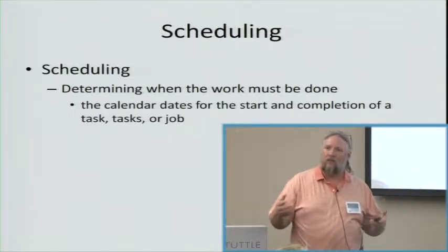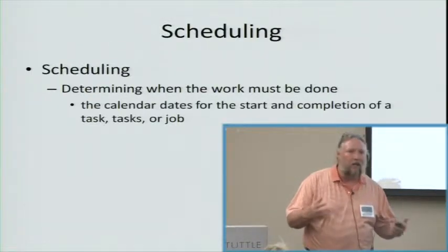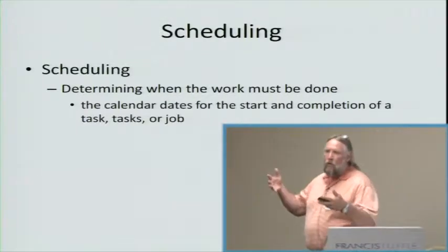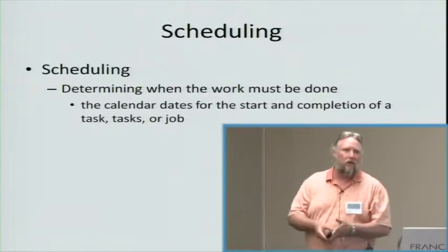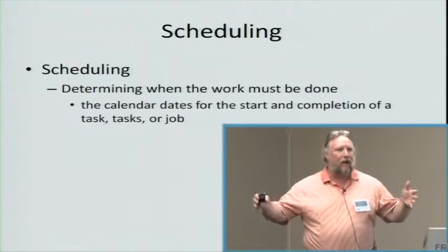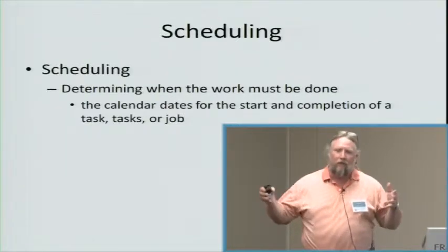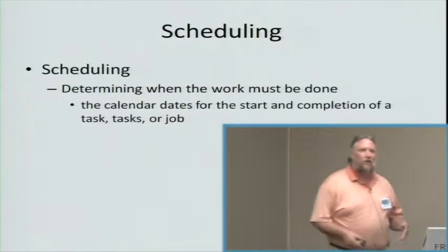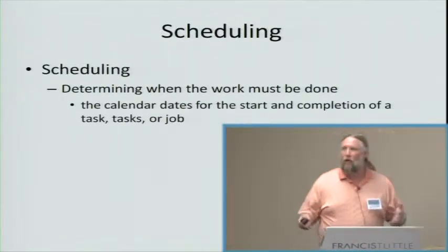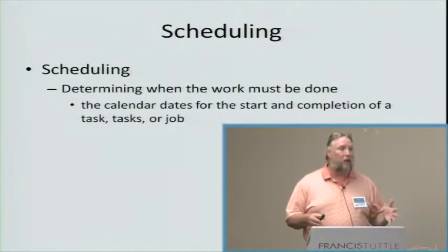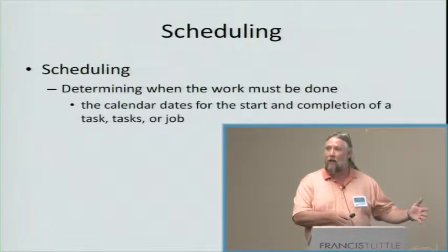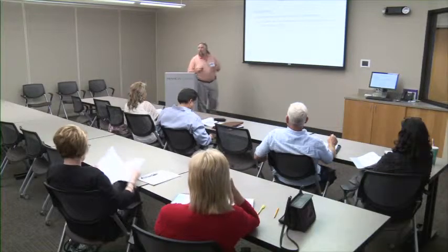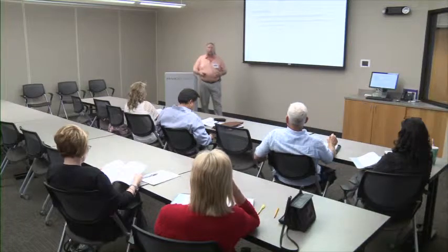How long is it going to take us to tie the steel? How long is it going to take us to pour the concrete? So now we've put some time rates on this with our plan, so now we have a time frame of how long it's going to take. If the time frame says we can do that in 7 days, and our contract says it has to be done in 5, then we go look at it and say we're going to have to figure out how to adjust our schedule to make sure we make contract. If the contract says we have 10 days to do it and it takes 7, then now we've got some time in our schedule that is good for us.